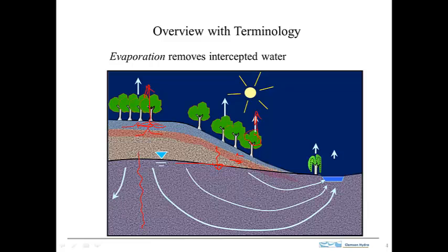This water flows up the trunk and goes out through the leaves and evaporates at the leaves of the trees, and this is quite an effective process at pulling water out of shallow depths in the soil. So this is a process where it's evaporation, but it's really the biological process of the trees that are contributing in a very important way. It's much more effective than just straight evaporation off of the ground surface at removing water from the shallow depth. So we call this evapotranspiration. It's kind of a long, cumbersome word, so ET is often the abbreviation that we'll use for that.